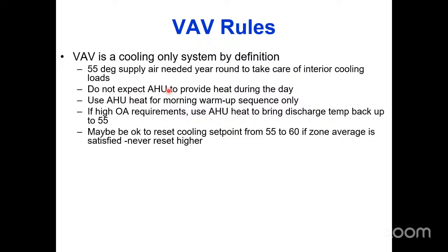With that being said, lots of manufacturers, including Carrier, which is a manufacturer we use at our office a lot, have VAV rooftops that have a dip switch on them that says occupied heating. You're like, oh, I can run heating in the middle of the day. Yeah, it'll turn on the heat in the middle of the day on a VAV rooftop for you. It'll do that. The problem is you don't really want it to do that. Because when you do, every zone gets heat, even the ones in the middle that want cooling.